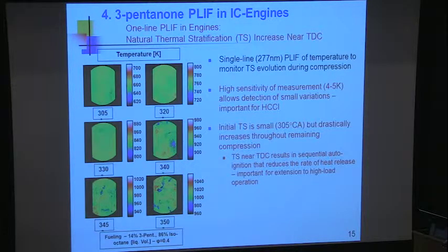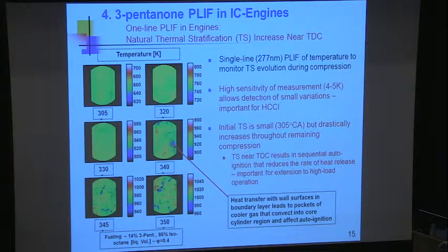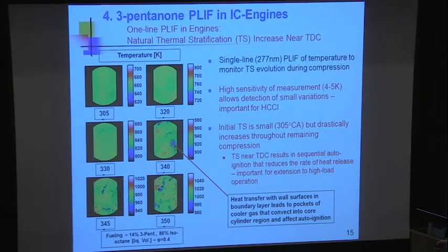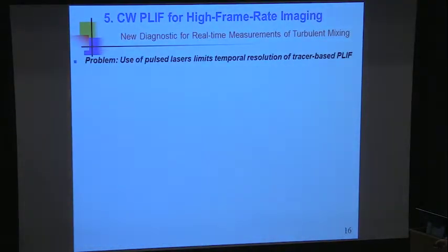And what's the problem with this? Well, it's a hydrocarbon, so if you raise it to a temperature above, say, 1,000 degrees, for more than a couple milliseconds, it burns. So unfortunately, it's not a universal tracer that you could use to test high temperature flows. The best we found is to use nitric oxide as a flow tracer, but it's toxic. They're really interested in heat transfer effects and whether the heat transfer was responsible for some of these cold spots. Those are the engine people.